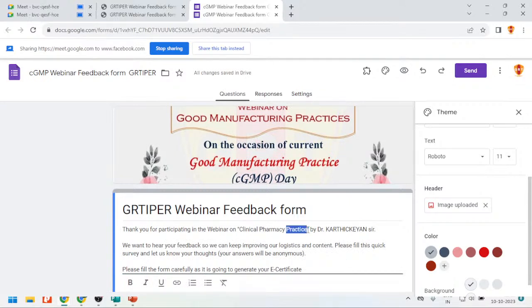Suppose you use one product today and tomorrow you want to use the vessel for another product. The washing and cleaning should be done with the specified detergent solutions. Afterwards they will be sterilized. Then samples are taken for traces and tested by quality control. If any traces are there, it is taken once again for re-sterilization and cleaning. Then once again we take up the final product storing, and the bulk manufactured solution is kept in the vessel.